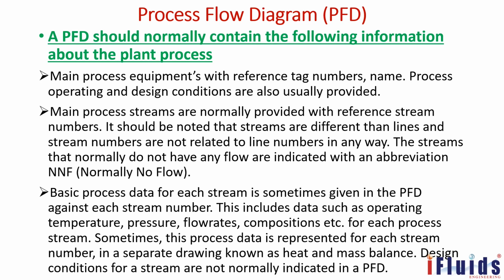There should be a stream number. Each stream has a number. One input to the column, distillation column or heat exchanger, one input stream should have the number, the reference stream number. It should be noted that streams are different from line numbers. We should have clarity.